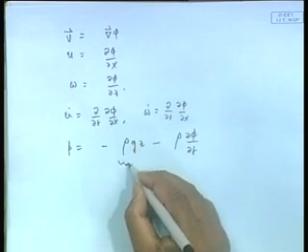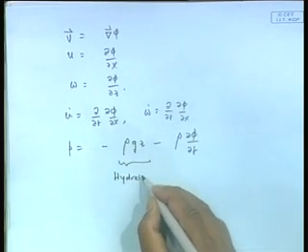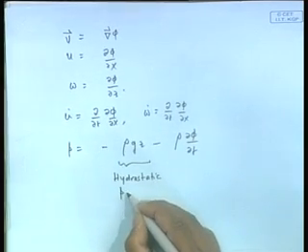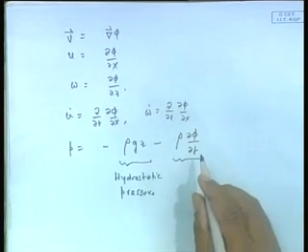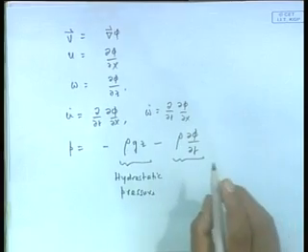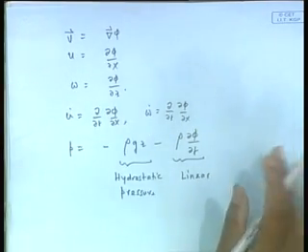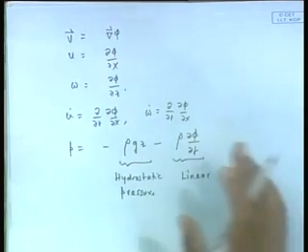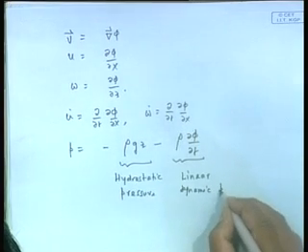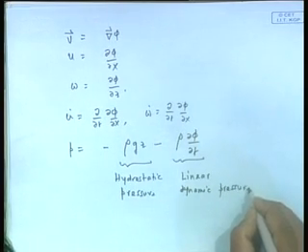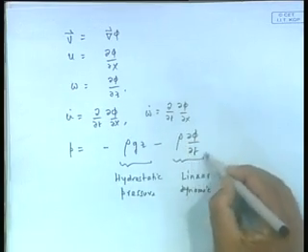In here this is my hydrostatic pressure, okay. And this is what is called linear dynamic pressure. Remember, linear dynamic pressure, the word linear because there was another term which was second order, which we neglected according to our linear wave theory. Now you find out that this linear dynamic pressure is gradient of phi in time.